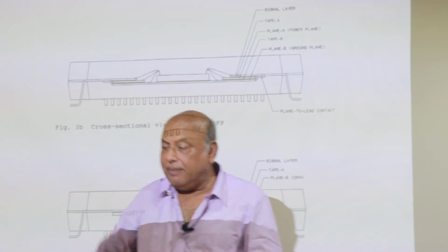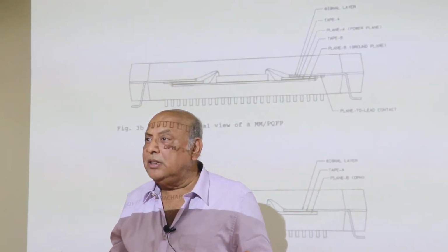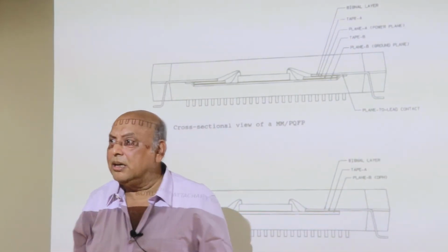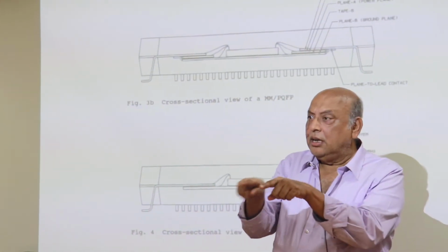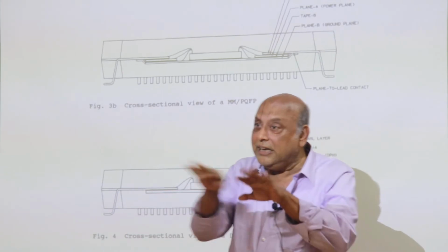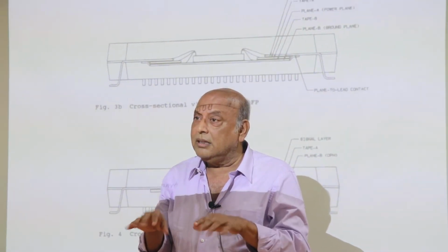So I built that lead frame stamped. The mechanical engineer, I worked with them, built something, I took the copper plate, I stamped it. Everything is out, the lead came out. And then I etched it to make it very small, very fine, and then I plated the tips. Gold plated, that little tip.